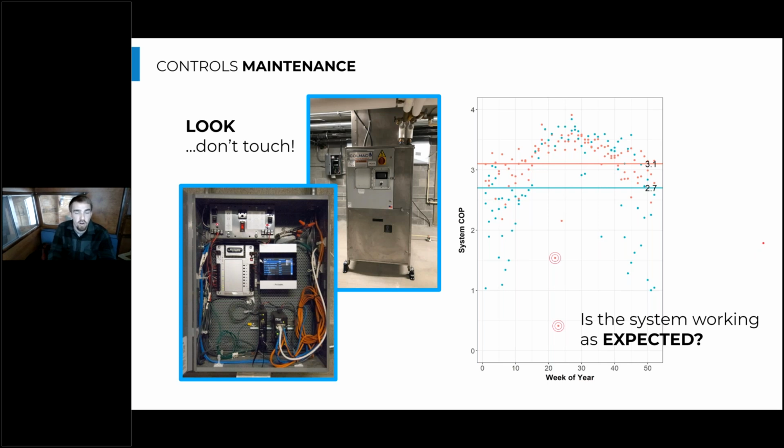So in terms of hardware, you don't want to touch it if you don't know what's going on, because there are physical electrical dangers. And in terms of software, you don't want to mess with any set points without coordinating with the manufacturers or the designer, and having a full conversation about why you're changing that set point from the one given around the original design intent.